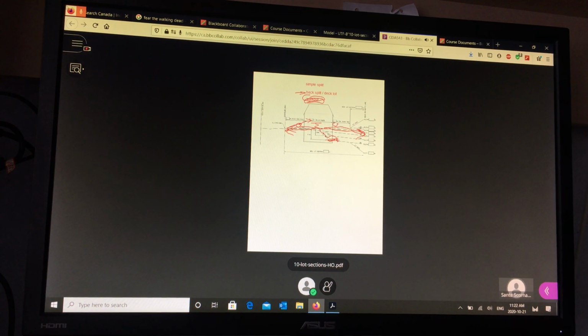It's going to get ridiculous. So sometimes the house acts like a retaining wall. You go in the front door, compatible to the grade at the front of the house, and then you walk down the stairs to the basement, and you walk out of the basement. If you can walk out of the basement, it's called a walkout, and it's usually a step down. If the elevation at the back is higher than the basement, but lower than the first floor, then you're in that back split or deck lot situation. And if the front yard and backyard are compatible, then they call it a simple split. All 3 of these are categories of split draining lots.